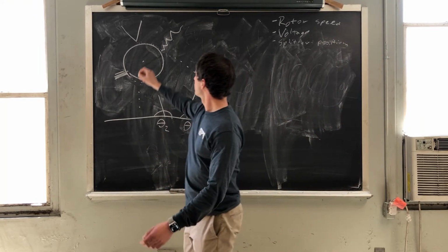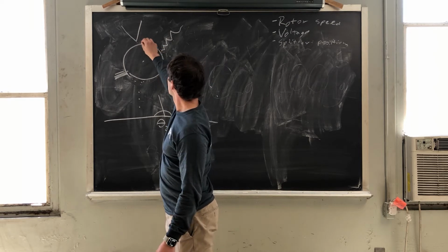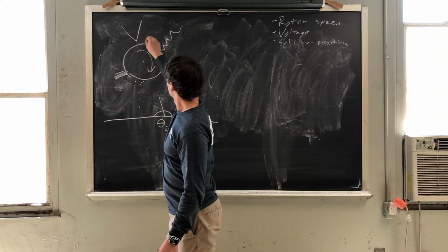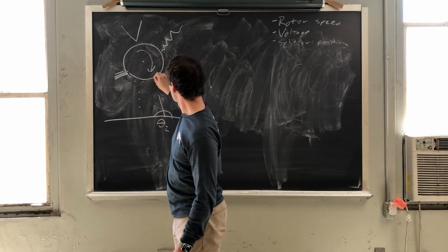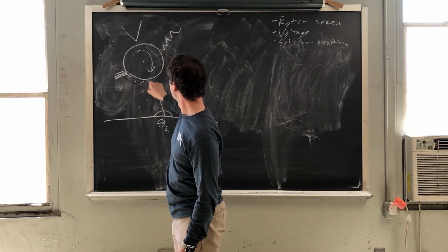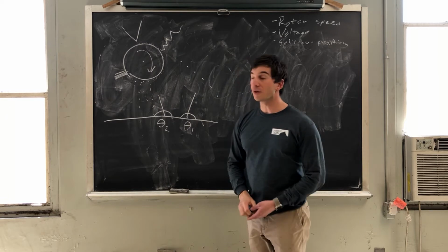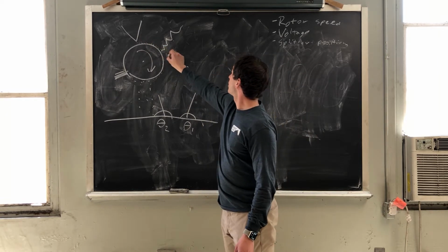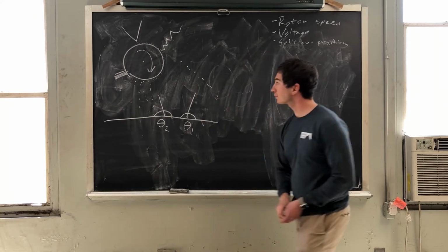Now, some particles, the gangue particles, attach to this rotor, ride the rotor around, and drop off somewhere here, ideally. Other particles, the titanium ones, just their inertia carries them this way.